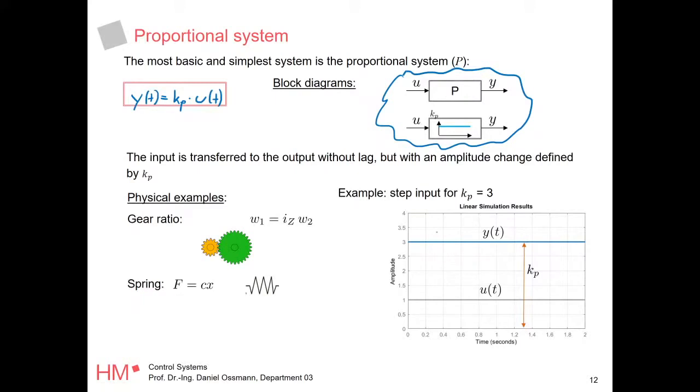These are now MATLAB examples, and here I did a step input. MATLAB usually gives you times larger than 0. As I said, you can simulate times lower than 0, so negative times as well, but we want to stick to times larger than or equal to 0. So this is now a step input. This gray line jumps to 1, and MATLAB then solves the output.